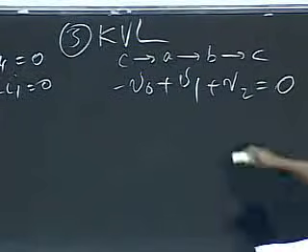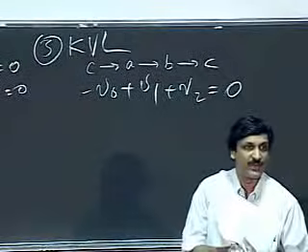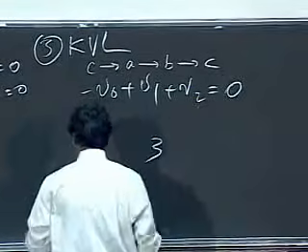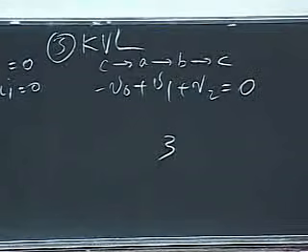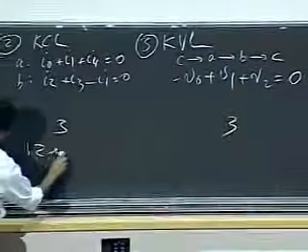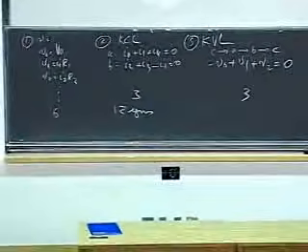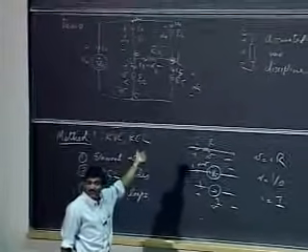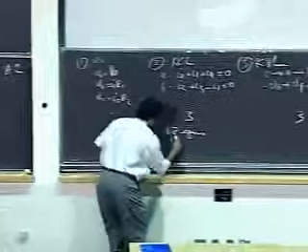All right. So in the same manner here, there are 4 loops that I can have, so 4 equations. Again, one of them turns out to be dependent on the others, so I end up getting 3 independent equations. So I get a total of 12 equations. There are 6 elements, a voltage source and 5 resistors. So there are 6 unknown voltages and 6 unknown currents. Phew. So I have 12 equations and 12